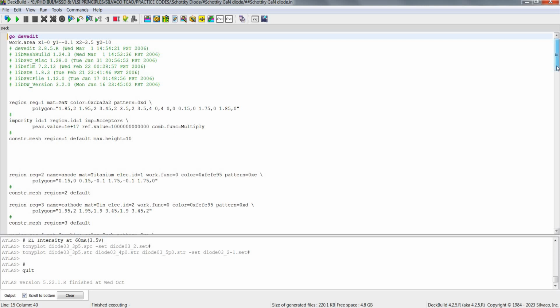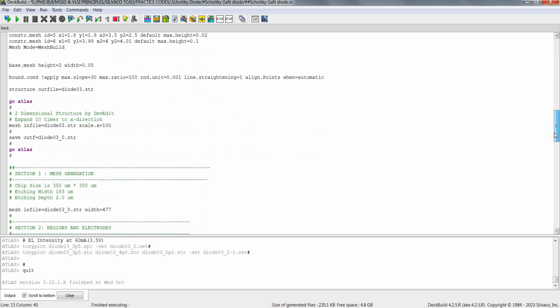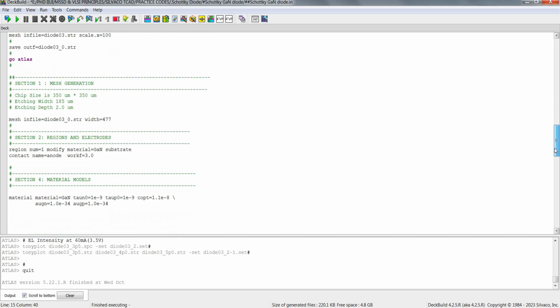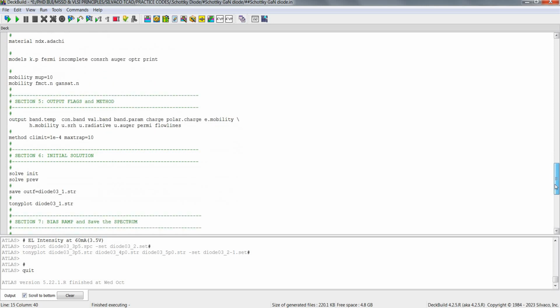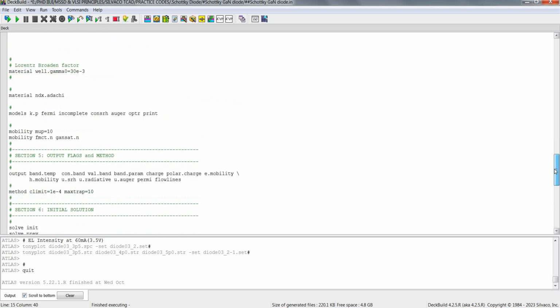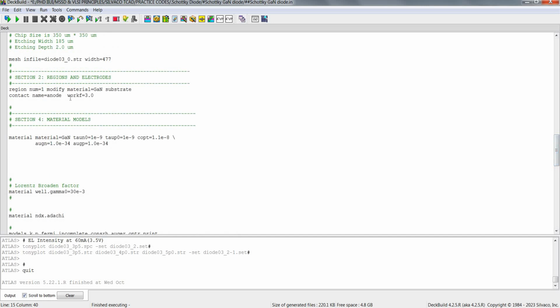And also the semiconductor work function should be less than the metal. The metal work function should be less than the semiconductor work function for this example. So let us make sure, but I'm going to make it around 6 electron volts. Let's not make it too low, because then the barrier would become too high. So assume a metal work function of 6.